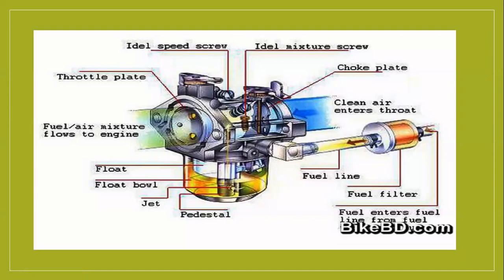Screwdriver. Right, there one cut is there. You can adjust the idle mixture screw. Then another screw is there. This is called the accelerator speed controlling screw. Idle means accelerator. This is called air fuel mixture.